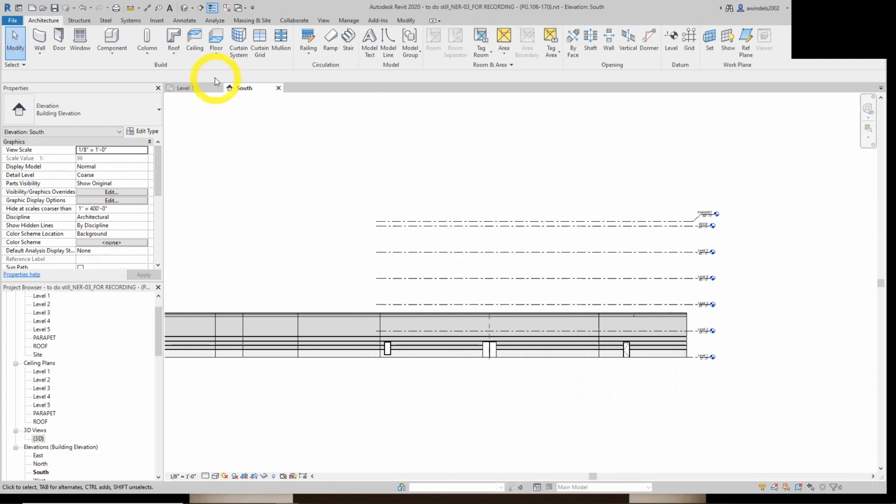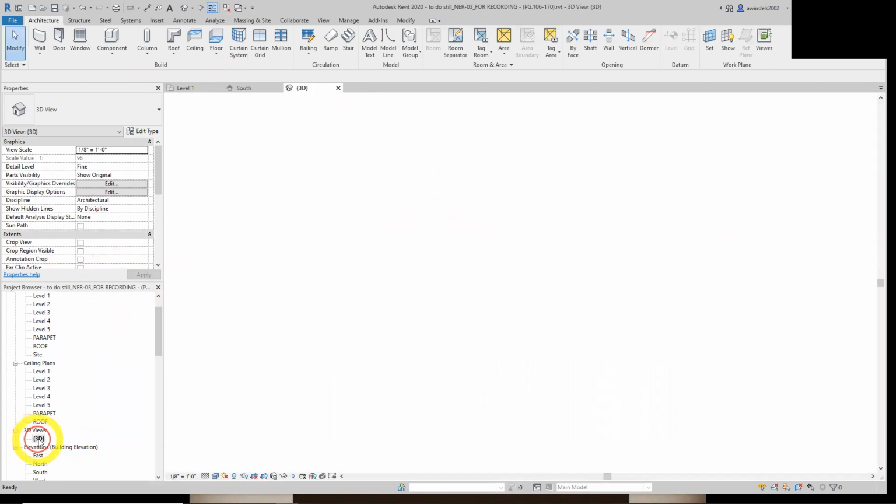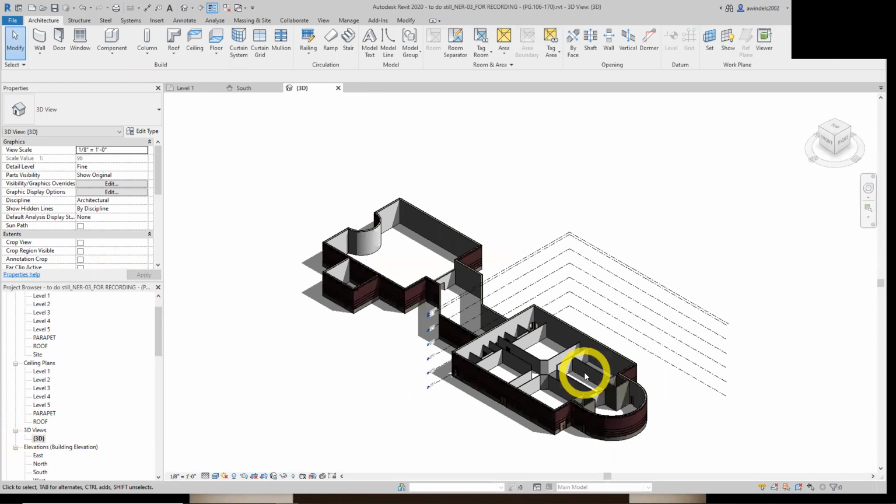We'll actually go back to that. It wants us to now do some work on extending walls up to different levels. So this one's kind of a step to pay attention to. The next couple steps, we're going to select all the exterior walls and extend them to the parapet level around our east side of the building.